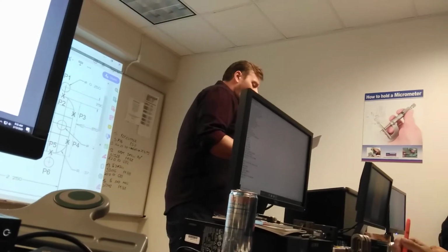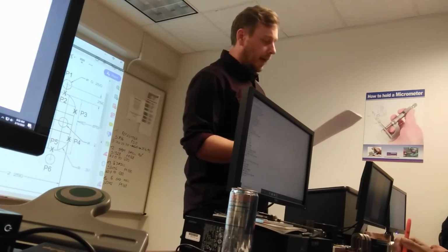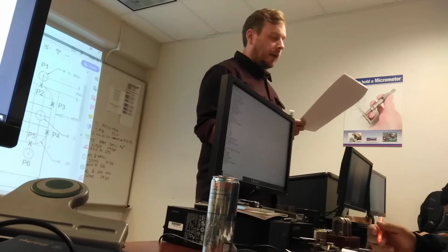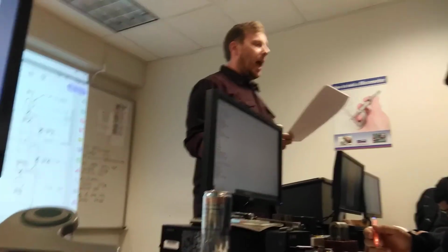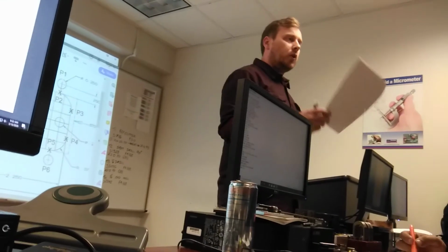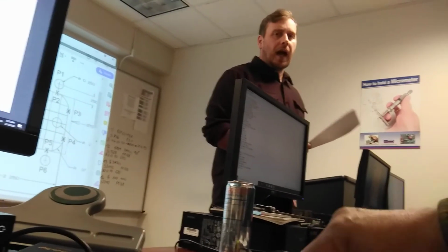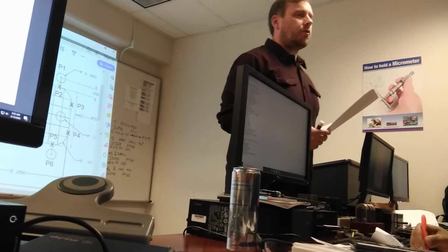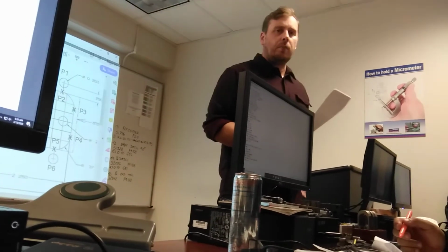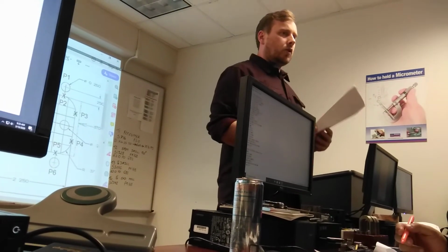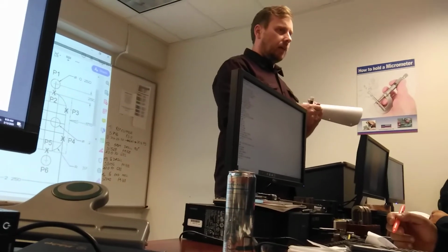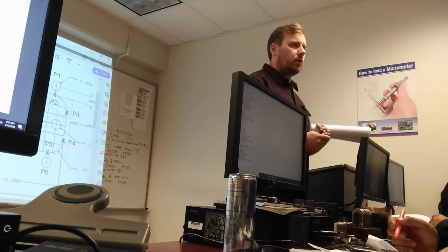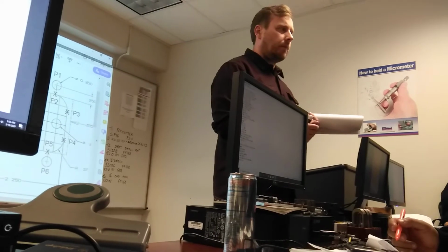When moving onto or off the part using cutter comp, it does not work if you try to turn it on with a Z axis move. So if you put G41 Z, nothing happens. Guess what happens next? You just scrapped your part because you didn't do the compensation correctly. So when you activate or deactivate, you have to do it with an X or Y. You can never use a Z. All right?